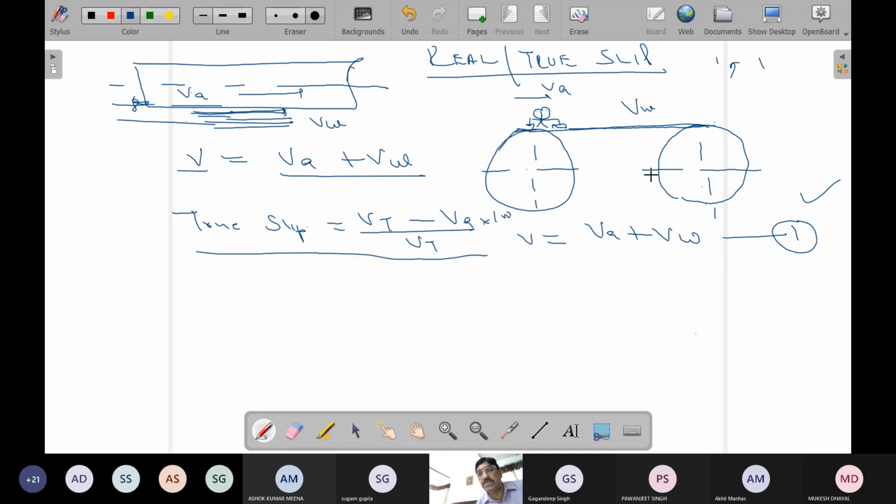It is on the same lines as we discussed here, but this VW is not because of wind, not because of current, not because of anything else. It is purely because of the friction between the hull and the water molecules. And this wake speed, what we have referred to here, is dependent upon the vessel speed. Correct? It has nothing to do with propeller directly. These waves are not coupled. So it is because of the friction, and that friction will depend at what speed the vessel is moving.